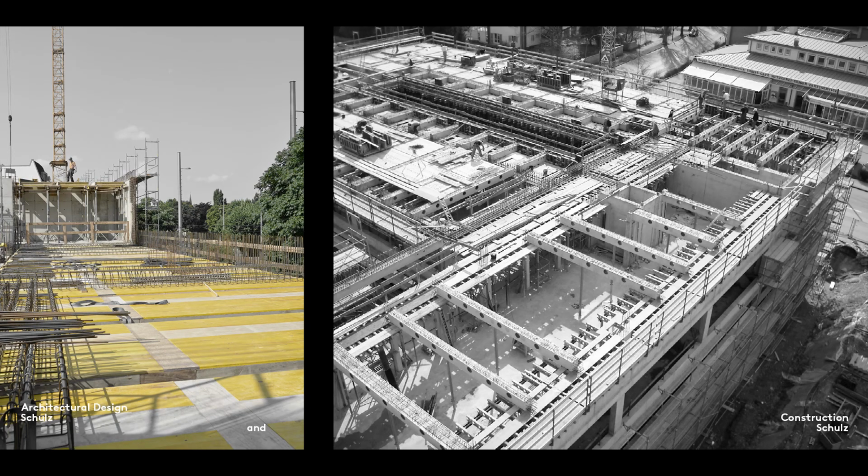Another important factor in designing solid floors, particularly in terms of cost-effectiveness and appearance, is whether they will be cast in situ or constructed using prefabricated elements. Slabs that are cast in situ require formwork into which the rebar is laid before the concrete is cast. Because wet concrete is even heavier than the subsequent floor will be, this formwork requires the costly and time-consuming erection of a supporting system. Prefabricated parts are produced in a concrete plant and installed on site, but have visible joints where panels butt together.